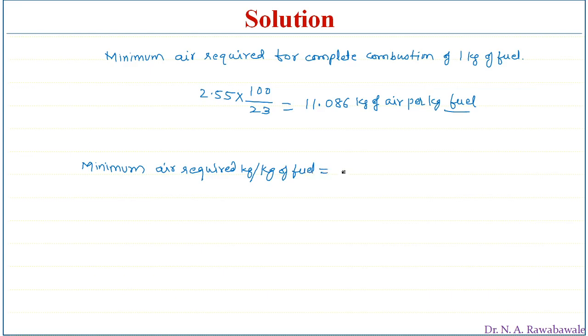That equation was 11.6 into C plus 34.8 bracket H2 minus O2 divided by 8, plus 4.35 sulfur.